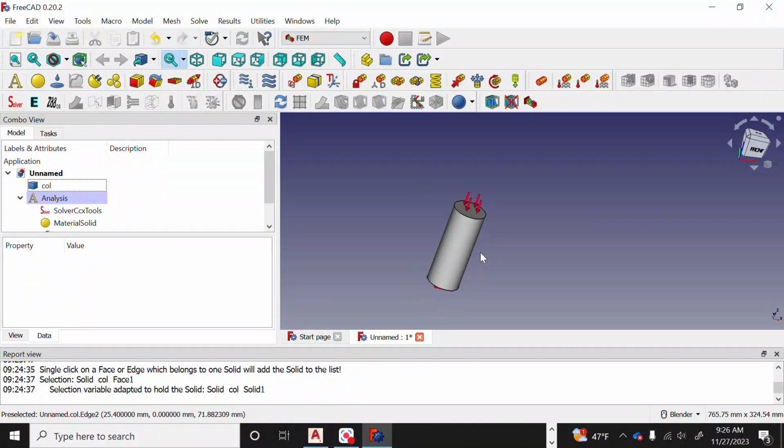All right, we have the boundary conditions. We're not going to have anything in the radial direction because it's going to be a column, not fitting. But you can do your study however you want. In this study, we're just going to do a column. Okay, the last thing we need to do is, I'm not going to do any thermal behavior. It's going to be room temperature, so it's not going to change temperature or anything.